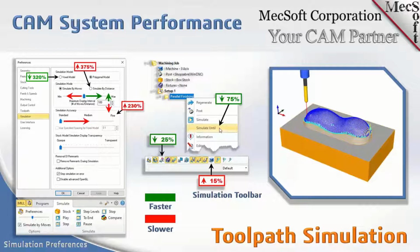But the minute you use different setups, as you might in a 4-axis setting or 5-axis index machining, then you cannot use the voxel model, because you're coming at the part and machining it from different orientations, and the voxel is inherently limited to the Z-axis of your toolpath. So as long as you're using just one Z-axis setup, where the tool axis is pointing only in one direction, which most 3-axis toolpaths are, then you can use the voxel model.